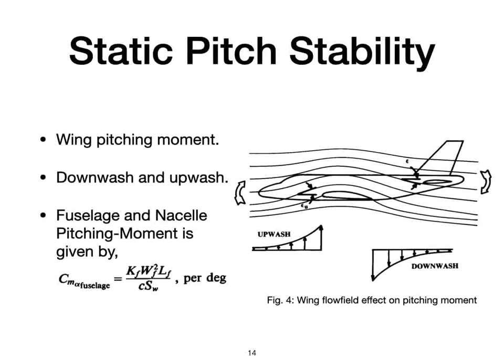Wing pitching moment. The wing pitching moment about the aerodynamic center is largely determined by the airfoil pitching moment. For a highly swept wing, the center of pressure of the flap lift increment can be ahead of the center of gravity, creating a positive moment increment. This reduces the download required by the tail.